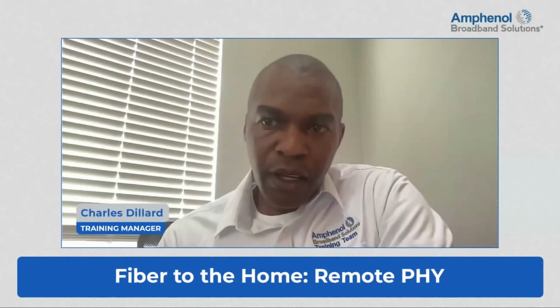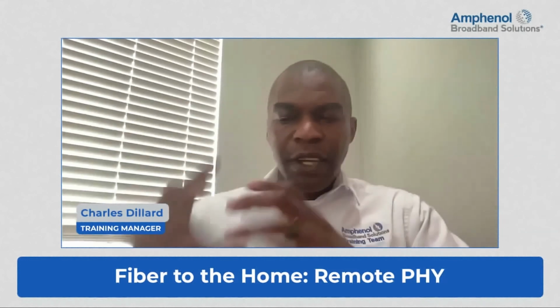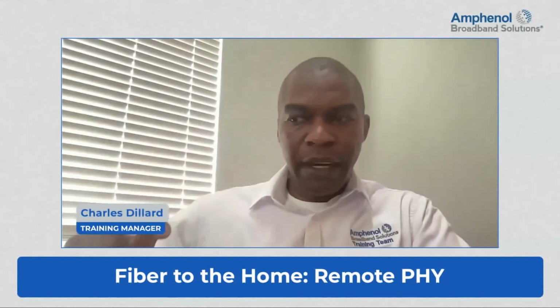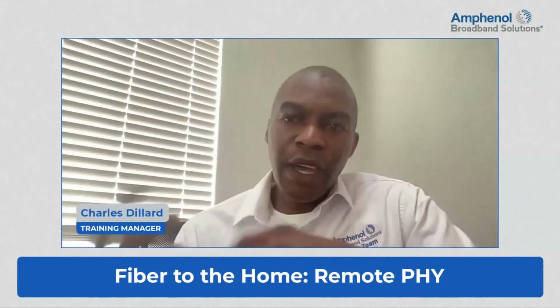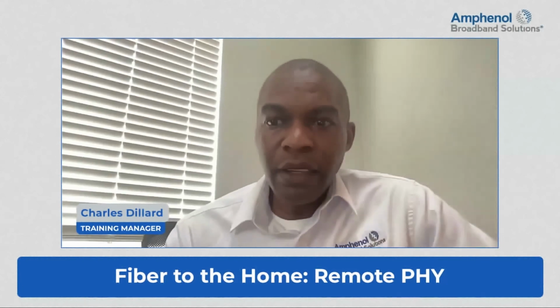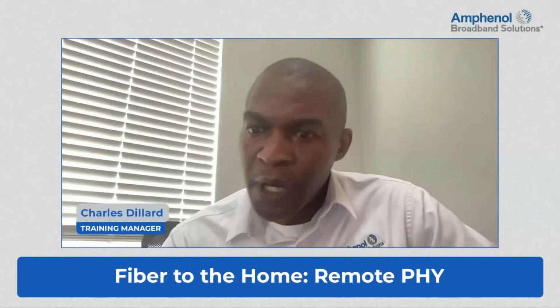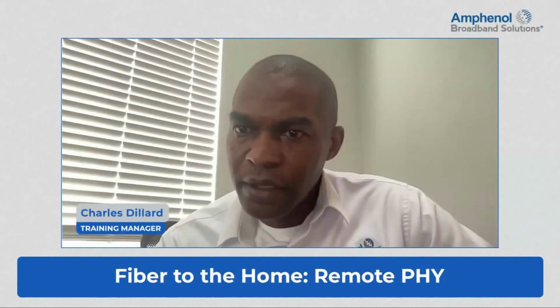What can we expect as a good SNR improvement? Great question. With remote PHY, we'll be replacing that analog fiber link with a digital link. What that means is that if your signal creation, the RF, is being created closer to the subscriber, that's going to help with the SNR issue that we currently have to deal with. Depending on what you read or who you talk to, SNR could improve anywhere from 7 to 8 dB compared to using an analog fiber link. And let's see if there are any more questions.